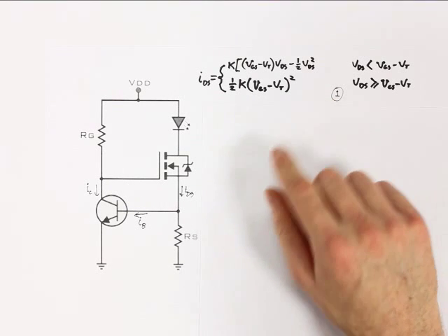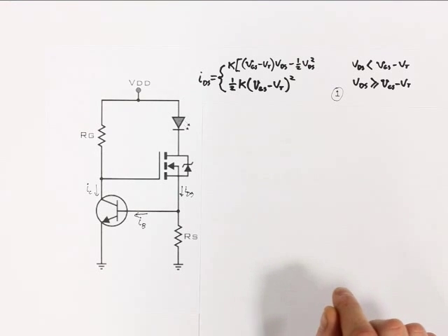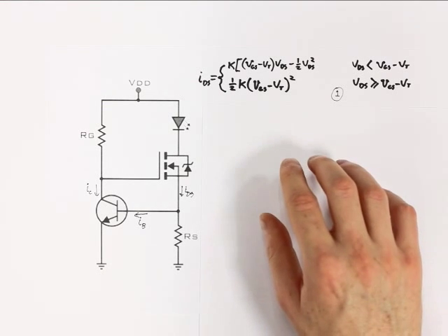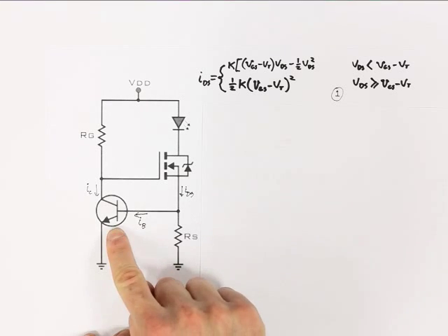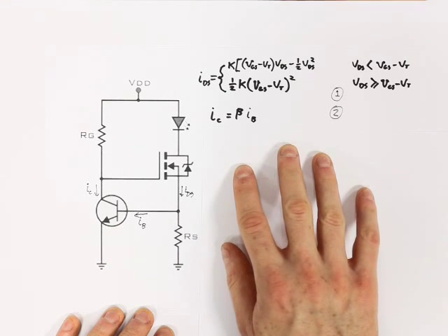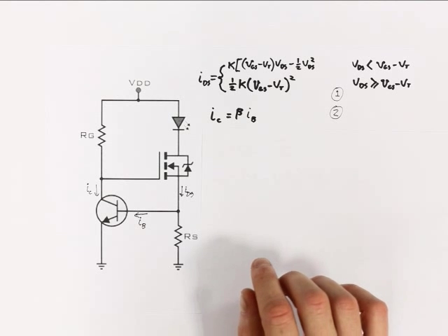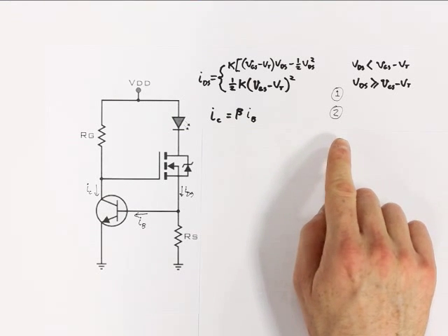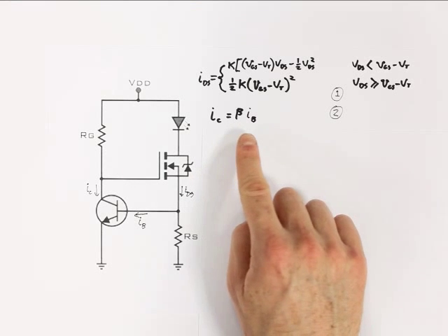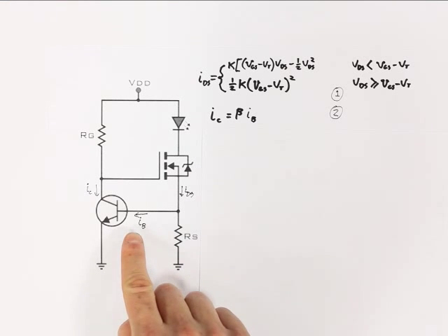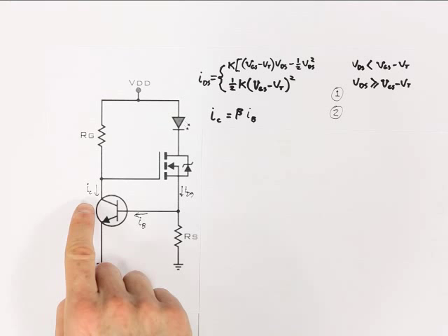So, a little bit complicated, but you're used to MOSFETs if you've studied 6002X, so that shouldn't be too unfamiliar. Next, we'll look at the behaviour of the BJT, which fortunately is much simpler, and we'll label this equation 2. Now, beta is the current gain of the device, so it's just a straightforward multiplication of the base current in order to get the permissible collector current.